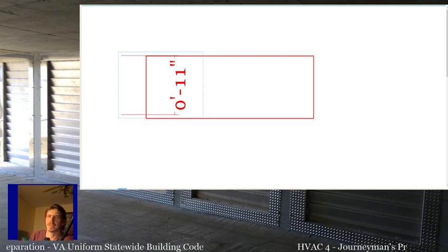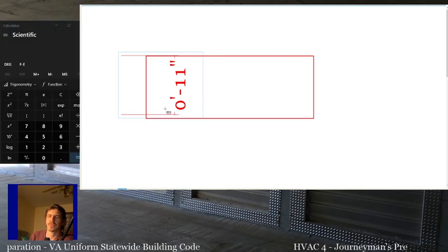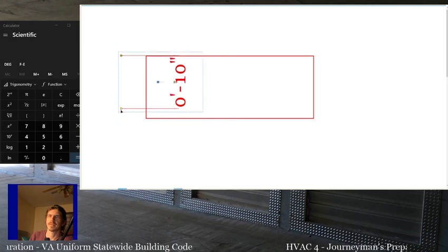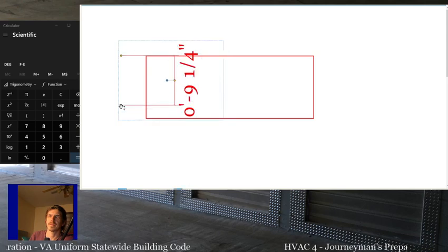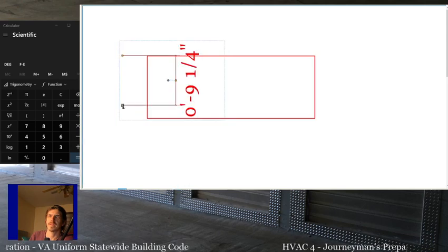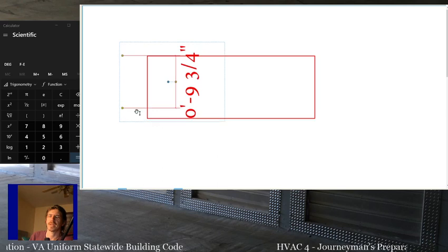Let me just go to a 1x10 because I'm almost certain that that's 9.5 inches. So if we have a 1x10, the first thing to understand is that a 1x10 is not 10 inches. It's closer to 9.5. And this changes for every stud size. So you're just going to have to kind of know that that's what's going on.